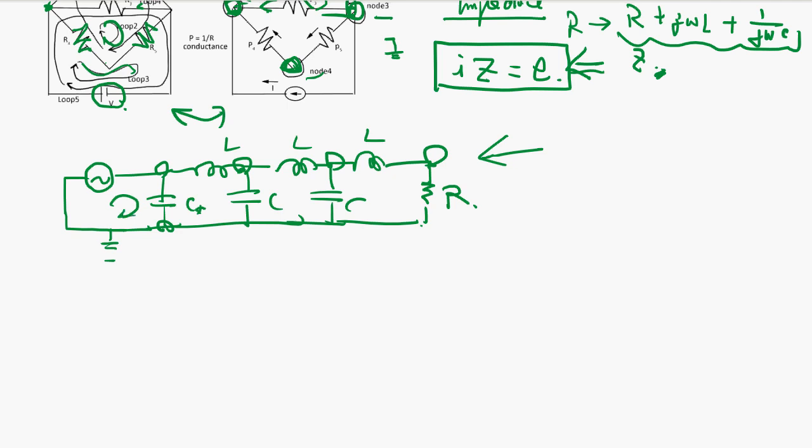Loop, you have to know the current of this. So 2, 3, 4, 5. How many currents do you have to know? Each branch, 1, 2, 3, 4, 5, 6, 7. Okay, so 7. So you need 7 loops. So in this case, maybe the node method is quicker because you have only 1, 2, 3, 4 nodes.